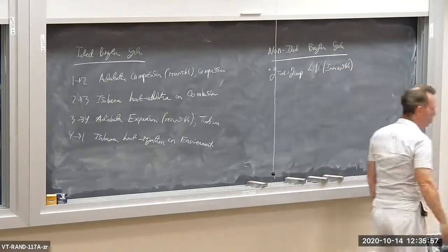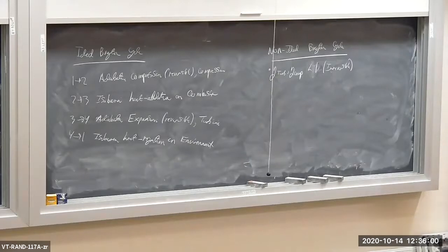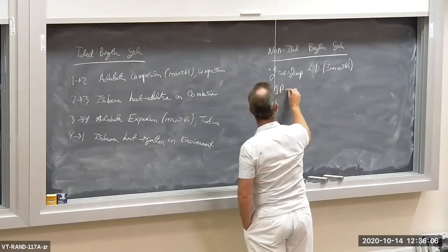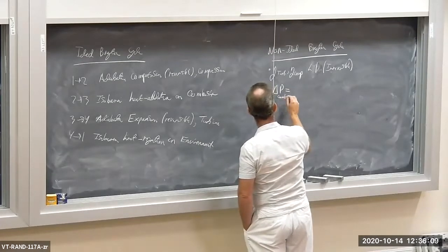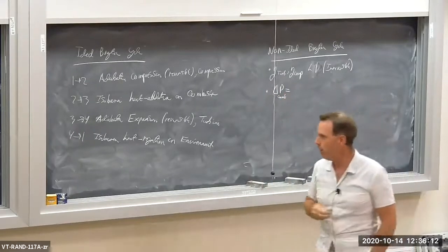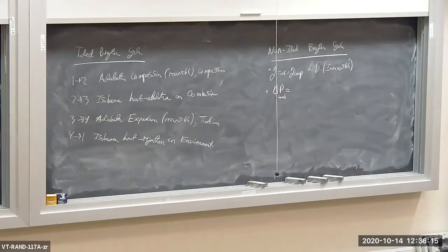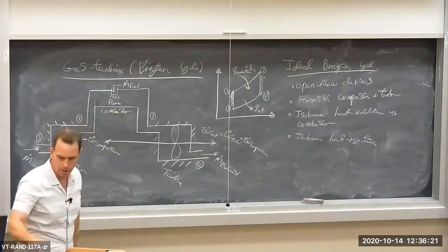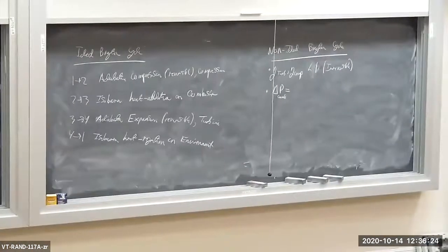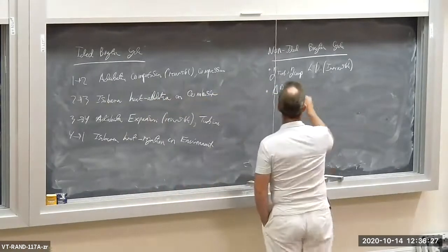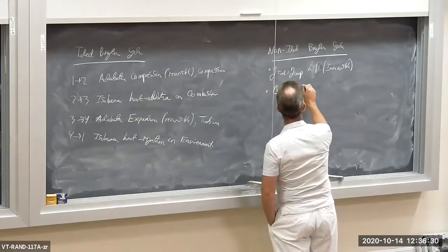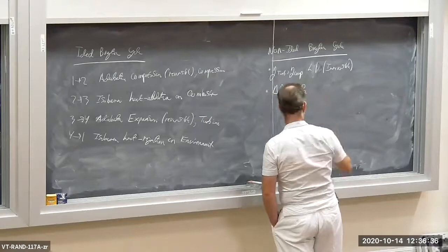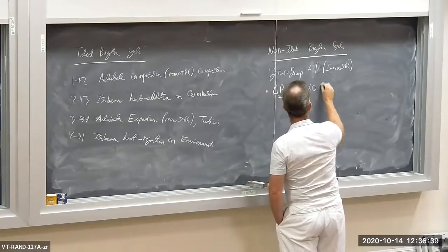We might have irreversible turbine and compressor operation. We also may have pressure drops across the combustor. Could be a delta P across the combustor. The combustion in the combustor occurs from state 2 to state 3, the heat addition in the combustor. So there might be a delta P, which is P3 minus P2. That may be less than 0. So there might be a pressure drop across the combustor.